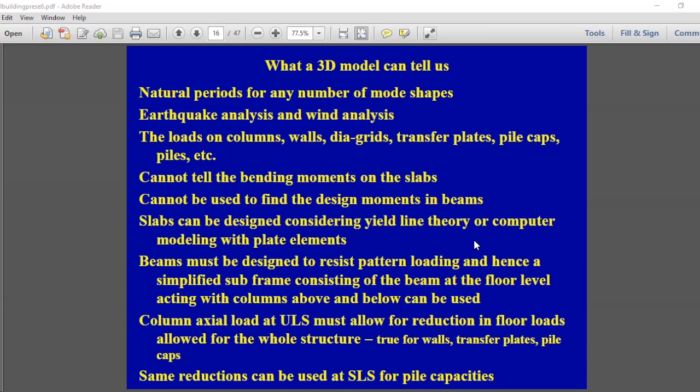And how do you design the slabs? Generally, one-way or two-way slabs we can easily design by using the yield-line method. One-way slabs can be considered as a one-way spanning beam, and then by considering 1 meter width, you can design it. In the case of flat slabs, you can design the flat slab separately without worrying too much about the columns and all that. If it is a solid slab, two-way spanning, you can use yield-line theory and design the slab.